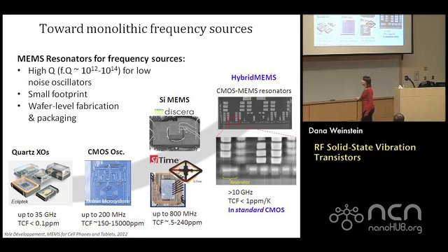your system. On the other end of the spectrum, we have LC tanks, inductor capacitor tanks, where you're sloshing not elastic waves, but electrons back and forth between an inductor and a capacitor, right? Now, these are super cheap, both in terms of area, you can fabricate these in the back end metals of your CMOS process. They're intimately integrated with your CMOS, so you don't have to worry about any sort of packaging, routing to the chip, anything like that. The problem is electrical losses are typically much larger than mechanical losses.